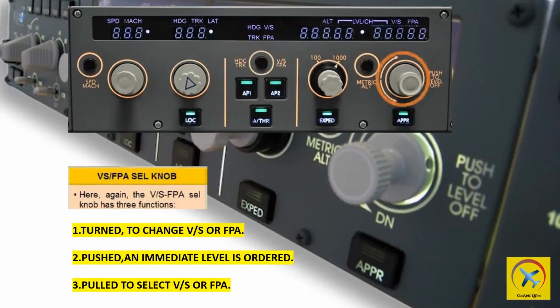When the selector is pulled, vertical speed or flight path angle engages. When pushed, the airplane levels off. When engaging a vertical speed or flight path angle, the selector must be pulled within approximately 45 seconds, or the selection is lost and dashes are redisplayed.